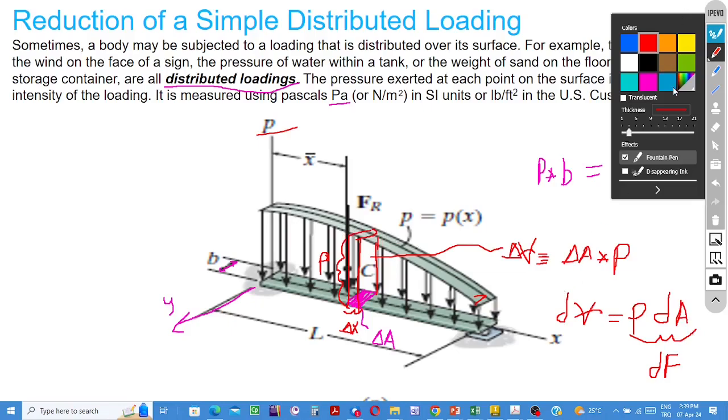So to be able to find the resultant of the given distributed load system, the thing to do is to take the integral from this point to that point, where the origin is over there, let's say, to this point. These are the limits of the integral. The result is the resultant force, F, of this distributed load system.